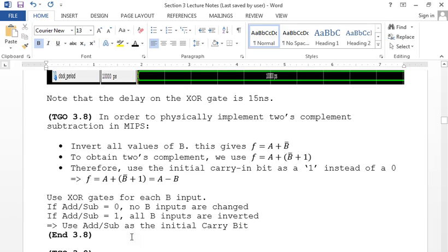So normally you'd have to do a full subtractor. Let's say I want to derive an arithmetic logic unit that did addition and subtraction, right? Before, if you're just designing one, you have to design a full subtractor and use a multiplexer, right? Which requires a lot of overhead. So I'm going to show you how you reduce this using the idea of flipping the bits like we did in 2's complement.